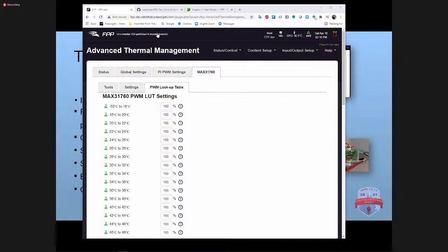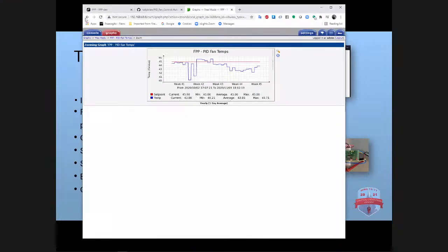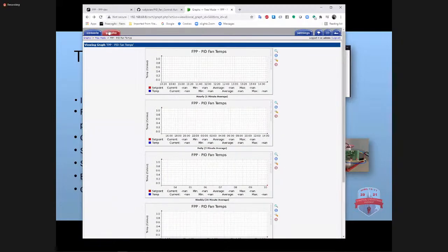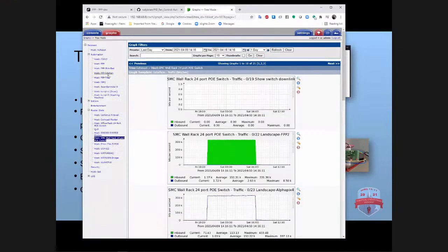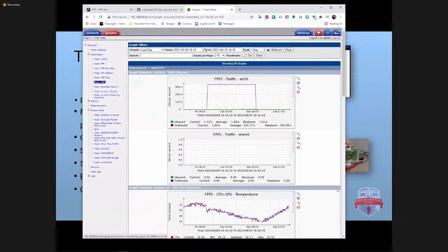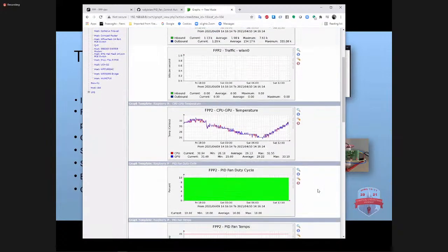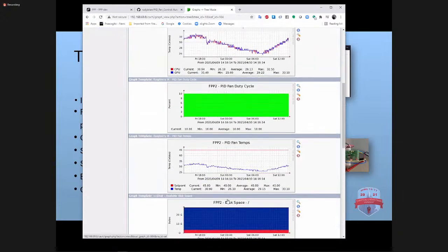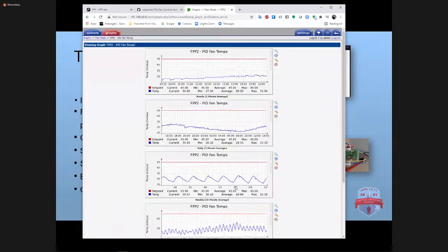That is pretty much it for this. I guess another thing I just wanted to show, because I kind of whizzed by this, one of the other features that's going to come alongside with this is the device will allow you to export your fan information and temperature information over SNMP. So if you have something like a monitor program, an NMS, you might have another tool that you want to use. This happens to be Cacti that I'm using here. It'll show you some of this stuff, your target temperature, your set point, your actual temperature range, so that you'll know if you're exceeding your temperature.